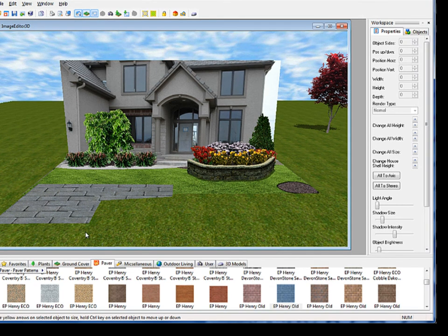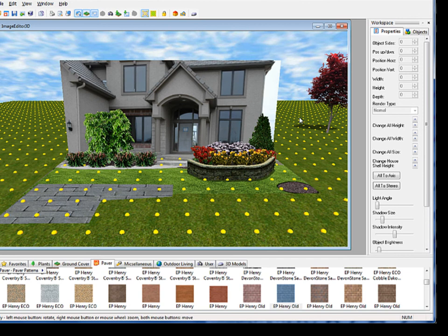Alright, now let's go ahead and adjust the terrain. What we want to do is add a berm in here, and we're going to adjust the ground plane terrain. We have up on the toolbar Enable Disable Terrain Editing. Okay, and that gives me several thousand yellow points across my terrain, which I can grab a point and pull up, just like pulling it up off the ground like so.